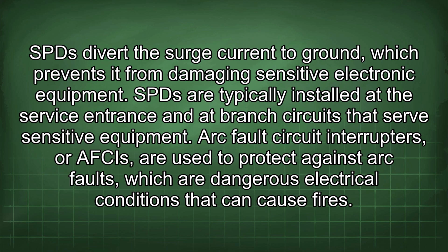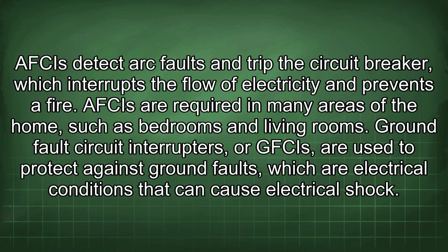Arc fault circuit interrupters, or AFCIs, are used to protect against arc faults, which are dangerous electrical conditions that can cause fires. AFCIs detect arc faults and trip the circuit breaker, which interrupts the flow of electricity and prevents a fire. AFCIs are required in many areas of the home, such as bedrooms and living rooms.